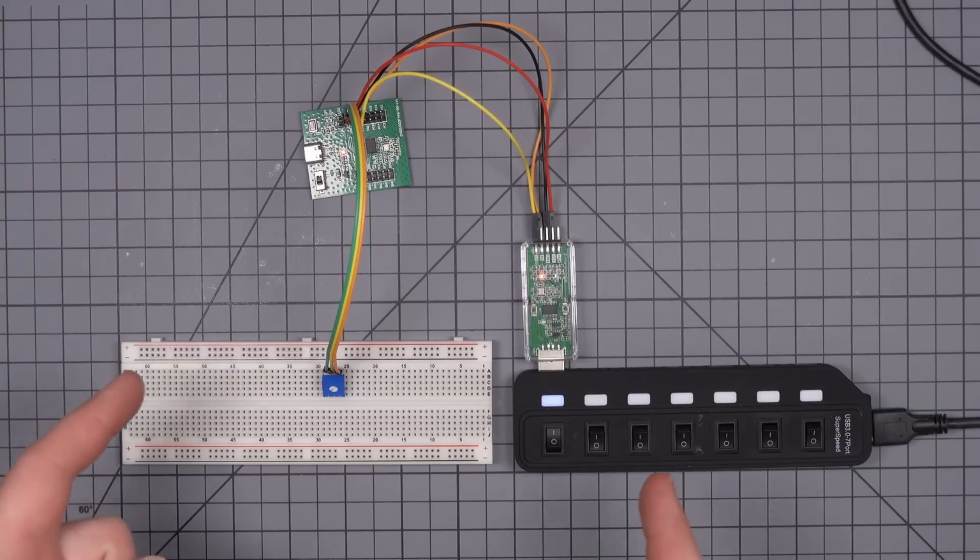This took a little bit of playing around because of the aforementioned lack of documentation on the HAL drivers. Pretty simple stuff like, should this field be 0 indexed or 1 indexed, and how do I do a single conversion since all the example codes are multiple or injected conversions? Overall though, I would say that this example took me a similar amount of time to what it did on the PY32, with my lack of familiarity with the drivers being offset by the fact that the UART was already set up. So here's the circuit setup.